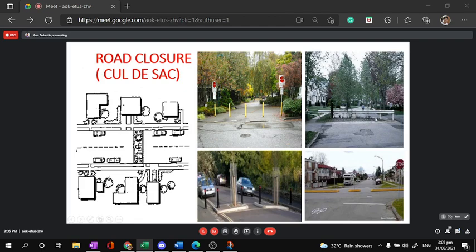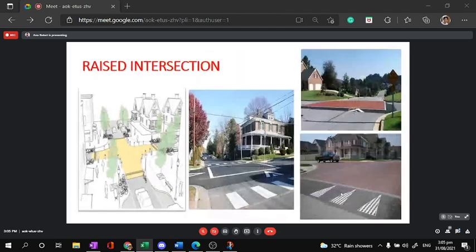Another enclosure is something like this. It may be good for walking pedestrians and cyclists, but certainly not for four-wheel vehicles coming into this other side of the lane. And this is also another one, very choked, with a barrier. So you can only move on this section. Expected, that's the dead end of the road for regular vehicular traffic. What you can have here is just motorcyclists, walking pedestrians, and bicyclists. So, the same here, no? It's important to realize that you can design infrastructure to improve the safety of an area by virtue of traffic calming devices and methods.